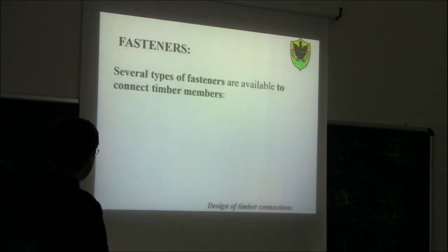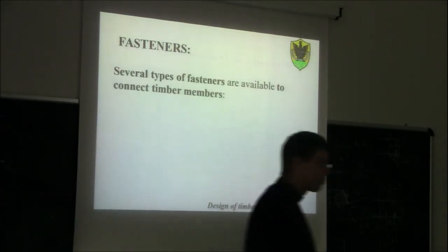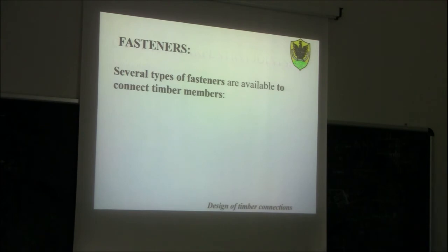Okay, so now I think we can go back to conclude our roof design. For the design I have interconnection. Now, strictly speaking, in terms of regulation, we should use Hankinson. However, we know that this other equation is much better. So my recommendation would be, you should first start with Hankinson. If Hankinson is fine, then okay.